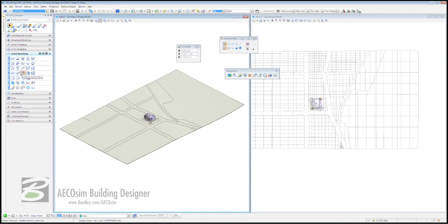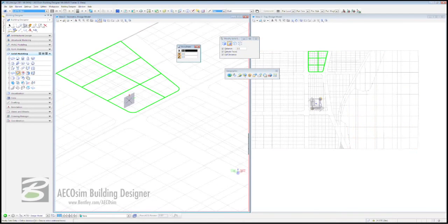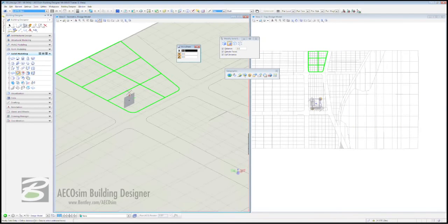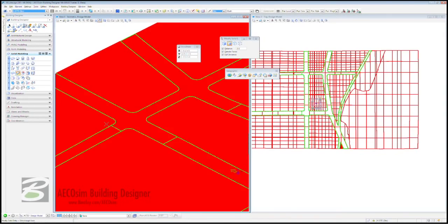We come to our solid modeling task again, and we come down 4 rows and to the second one in, Modify Solid Entity. In the Modify Solid Entity dialog box, choose the second icon in from the left. Also make sure distance and extrude faces are checked, and in the distance, you can enter in the value of 8, to be 8 inches. Because what we're going to do now is select one of the areas, you move your mouse inside of it, click once more to accept that, and then you just raise that up by a matter of 8 inches, like a classic curb.